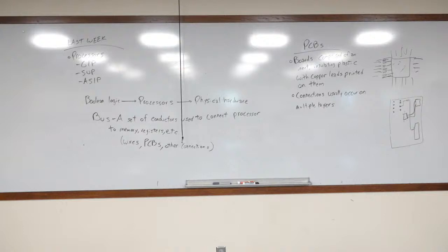Any PCB designer is going to run into this struggle. How do I make sure that these wires don't cross? Because as soon as they cross, if all of those were printed, all of those are connected, which basically does nothing now, because all of them are trying to send different types of information. It's fine when they're all connected to like 5-volt power. It's fine when they're all connected to ground. It is not fine when this one's trying to transmit data and these are also. Or this one's 5-volt power and this one's trying to transmit data. It is not okay in some applications for these wires to cross.